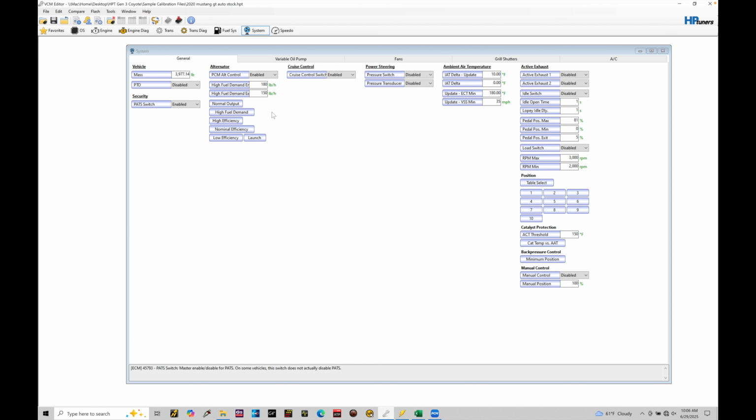What that means is the battery voltage, obviously, if it had no alternator charging against it, it would sit, let's say, roughly at 12 volts. That could be a little bit lower, could be a little bit higher, but roughly 12 volts. When we're running our engine, idle, part throttle, full throttle, we want it to charge at a higher battery voltage. The standard is about 14 to 14.5 volts. So the system works looking at the desired charging voltage that we specify from any of these tables here.